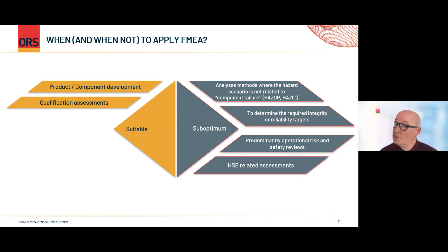So absolutely you should use it for that. Not so good on the right hand side if we try to apply it where the hazard scenario is not related to component failure. So something's not broken or failed, but we could still have a hazard present, and a HAZOP or hazard study would be more appropriate for that.